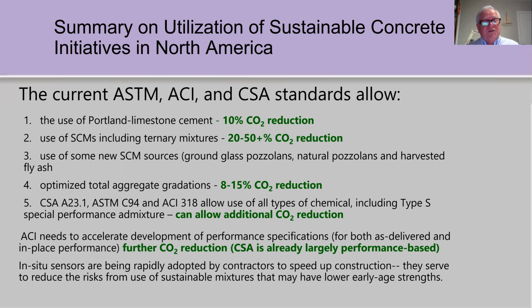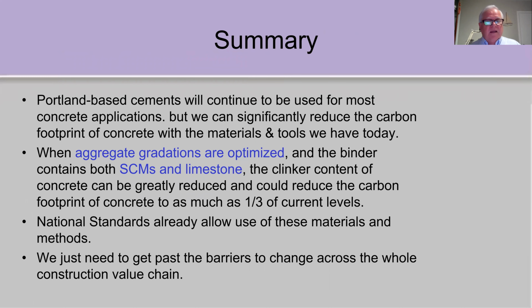Wireless in situ sensors are really cheap now, and people are adopting them on construction sites everywhere. Through the temperature and time curve, maturity allows people to estimate the strength of their concrete in situ, and not rely on cylinders and cubes in the laboratory at constant temperature. Typically in the structure, unless you've got very thin slabs, the concrete is going to get stronger faster than indicated by the lab tests, which means contractors have adopted this technology because it allows them to accelerate construction. And that's money.